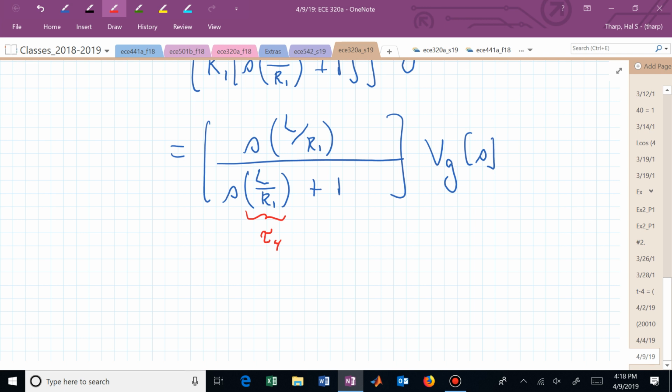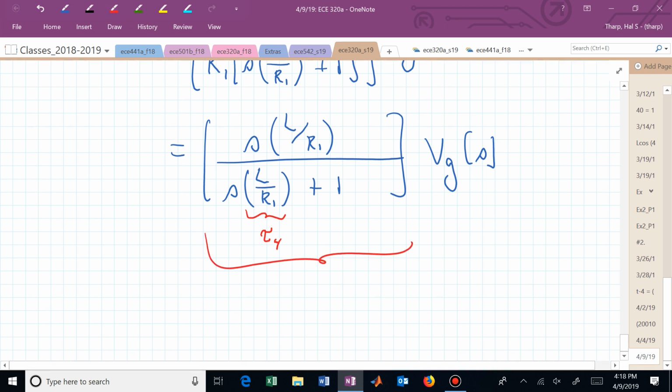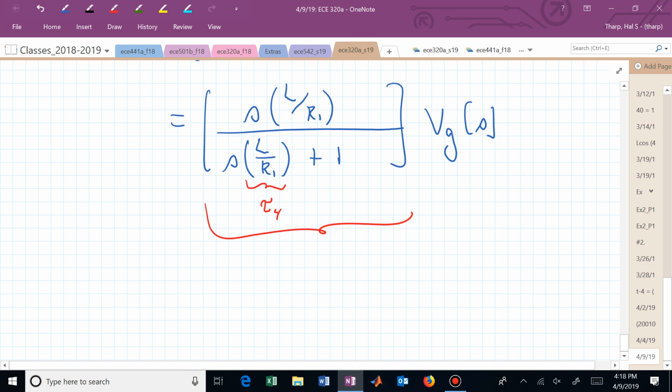And this entire transfer function, is that pole zero form or time constant form? Can you explicitly see the pole? Well, you can, but you're doing some calisthenics or exercises in your mind, more so than it's just jumping out at you. You solved that for S to find your pole. But now it's in time constant form, isn't it? Because the constant has been normalized to 1. This is now our time constant form.